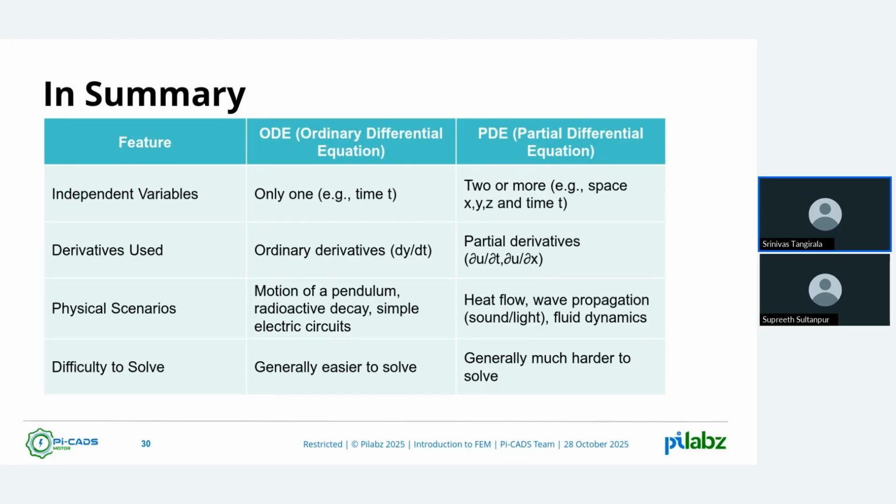Okay, first is the geometry creation, second is the meshing. Meshing involves different types of elements. It could be triangular, it could be tetrahedral, depending on the type of element that you use. You have the choice. If the type of element is more complex, it takes more time. If it is a simple triangular element, then there will be fewer nodes and fewer elements, which results in a faster simulation. But fewer elements and nodes give you less accurate results.